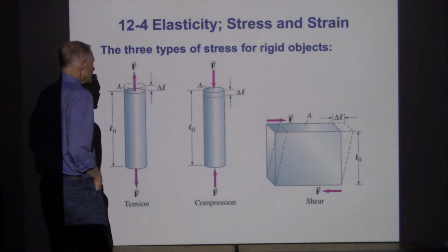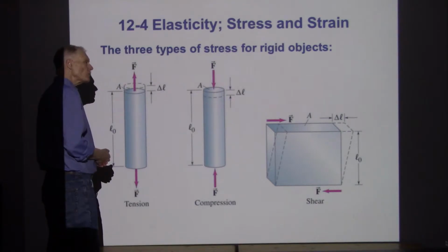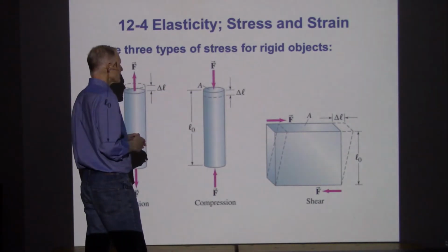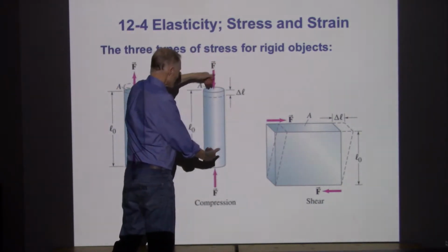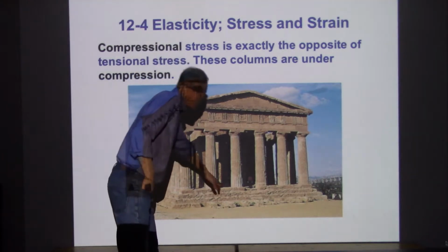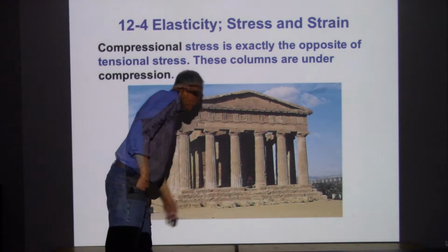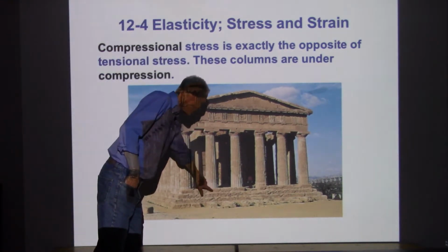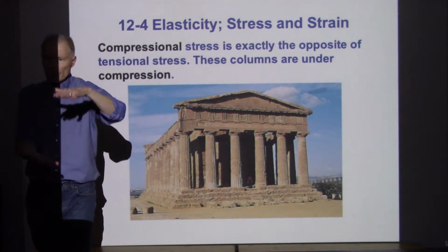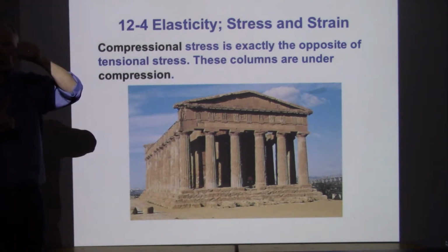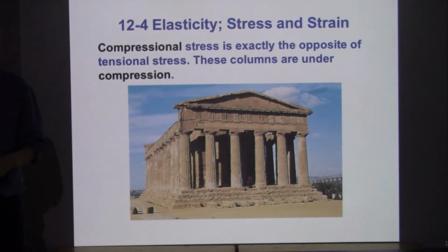So in this case, if I'm building a building, if I'm just stacking things on top, the forces are going to be tending to compress objects. So if we go back and look at this building one more time, right here, we could ask, well, what about the stone here at the floor? What's going on with that? Is that under compression? And we would say yes. Where the columns come down and are resting on that floor, the stone underneath is also being compressed. It's being pushed up by the foundation and pushed downwards by the stone, so it's caught in the middle. It's also going to be undergoing a compressional stress.